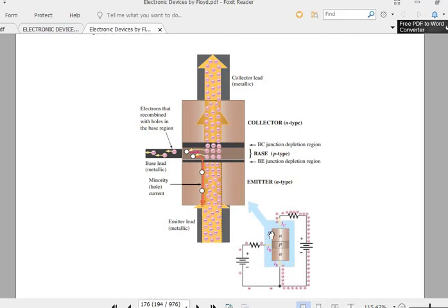So in this way, by using this configuration, one part is in forward bias, the input part is connected with the forward bias, and the second part, in reverse bias, is used as the output part, where the emitter is common in this particular configuration, remember. It is quite possible that another two topologies or configurations are also available, which are known as common base and common collector configurations. Depending upon the applications, obviously these circuits behave in different modes.